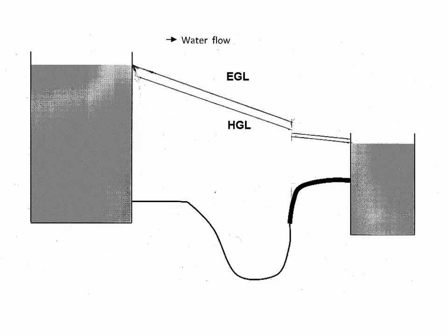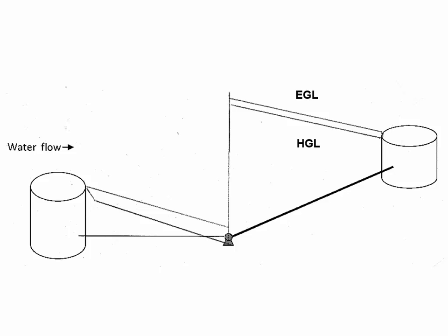Are there other questions about the first one? Here's the other one. How do we know that this is a pump instead of a turbine? Yeah, the water is flowing up. So here is a tank that's low. Here is a tank that's elevated on the right. And the arrow says the water is flowing from the lower tank to the higher tank. So the only way that can happen is if this device is a pump. It wouldn't work if it was a turbine.